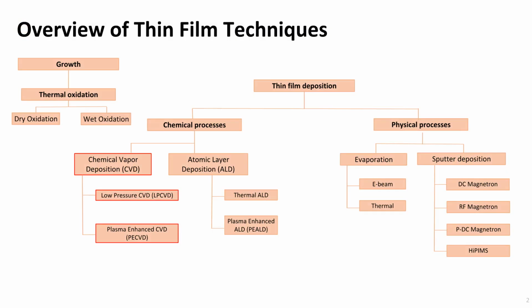Chemical vapor deposition is parent to a family of processes whereby a solid material is deposited from a vapor by a chemical reaction occurring on or in the vicinity of a normally heated substrate surface. It is used to deposit high-quality, high-performance solid films. The deposition usually occurs through a continuous process, where the deposition rate is influenced by various parameters like temperature, pressure,